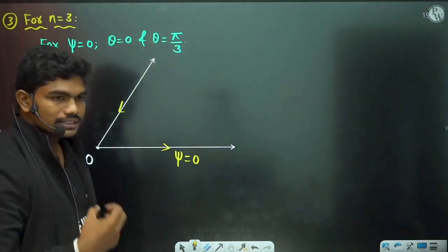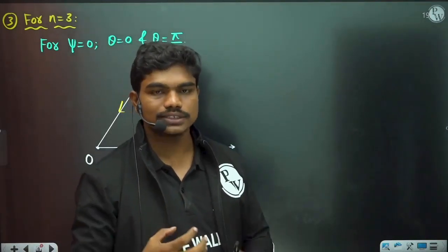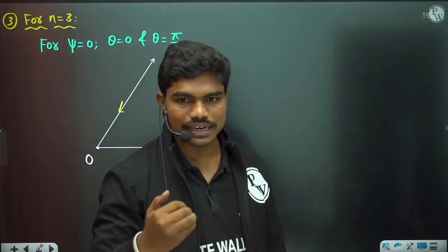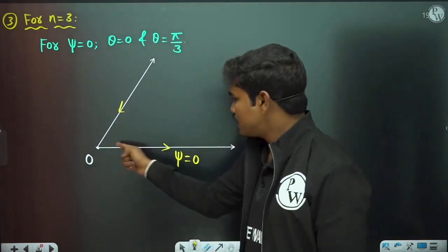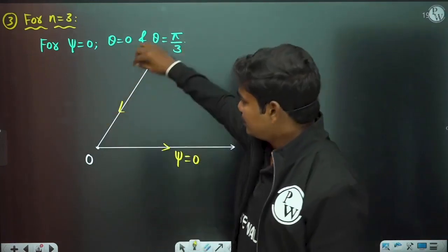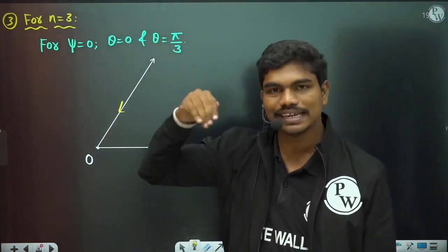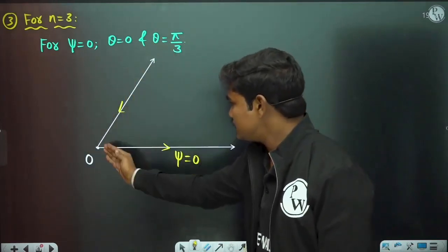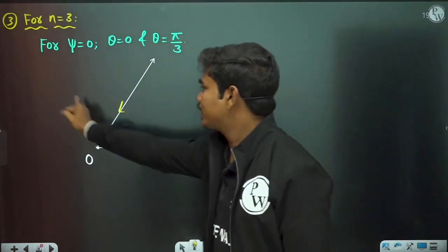So like this, the equation z power n will actually give you the case of flow in a sector. Are you physically understanding why this is called flow in a sector? Because along this streamline there cannot be any flow and there is no movement of fluid along this particular streamline. So practically we are assuming that stationary line of fluid as one solid surface, because practically fluid cannot enter this.